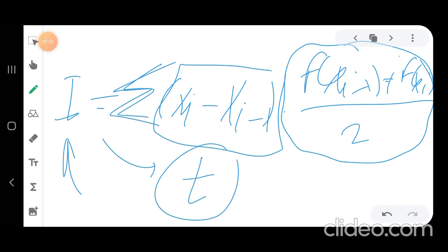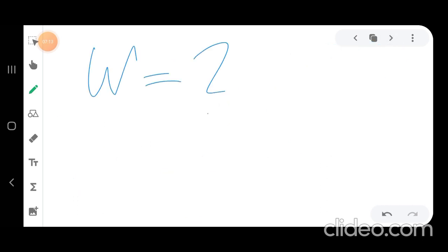Now what about w, if you are interested in getting the final amount that you are left with in the still pot after distillation finishes? How do you get this? The easiest way is to apply the equation that we derived before for the material balance, which is this equation. No need to use the Rayleigh equation, waste your time and integrate. You will get the same answer, or somewhat close. But the easiest way is to apply this equation.